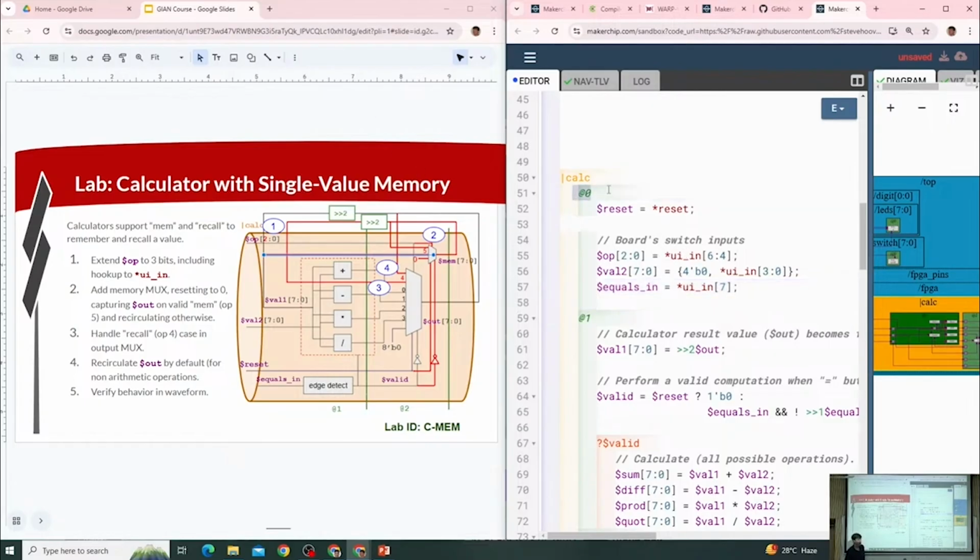So there's nothing special about 0. It just happens to be the number that has the first bit of logic in this pipeline. Everything in TL-Verilog conceptually is part of a pipeline. TL-Verilog does allow you to put expressions outside of pipeline scope like this. All that means is foo falls into a default pipeline in stage 0 of that pipeline.